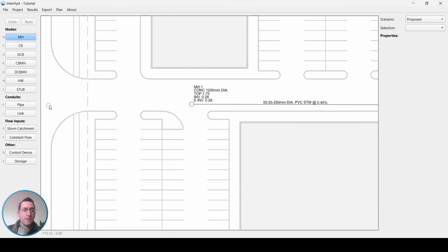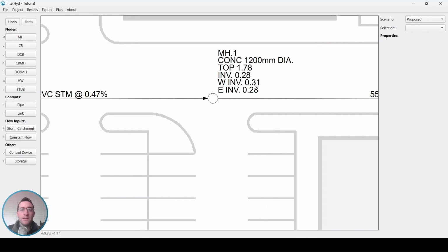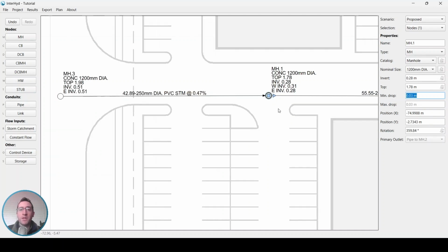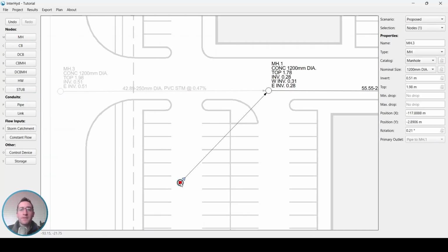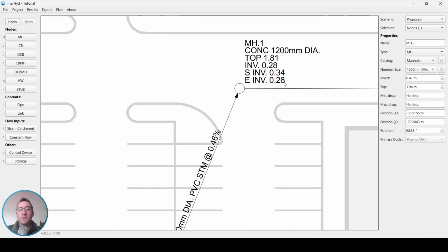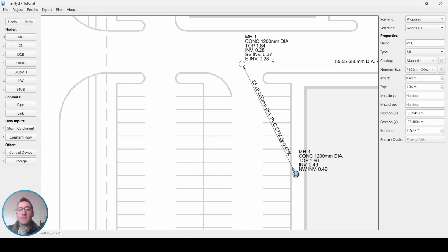So if I add in another pipe here, you will see these inverts, there's a 3 centimeter drop between them. You can actually click on this and you'll see that drop there as 3 centimeters. Now, if I pass this, so this would be a 0 deflection angle. This would be about 45. And if I put it sort of past 45 but before 90, you'll notice we now have a 6 centimeter drop. If I go past the 90 mark, this is now a 9 centimeter node drop.